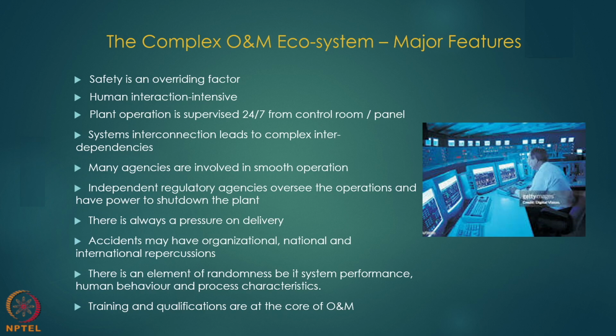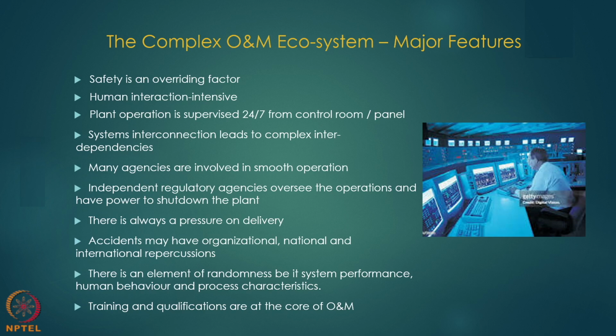So, no to the accident, and that's why I will give you a simple example. For a nuclear power plant, the risk assessment shows that the probability of core damage is less than 10⁻⁶. That means this is one level. Then they have barriers, so again a factor of 10, so 10 to the minus 7. And then finally the public domain, so further it is reduced. That is the kind of system that is built to ensure that the hazard doesn't reach the public domain.